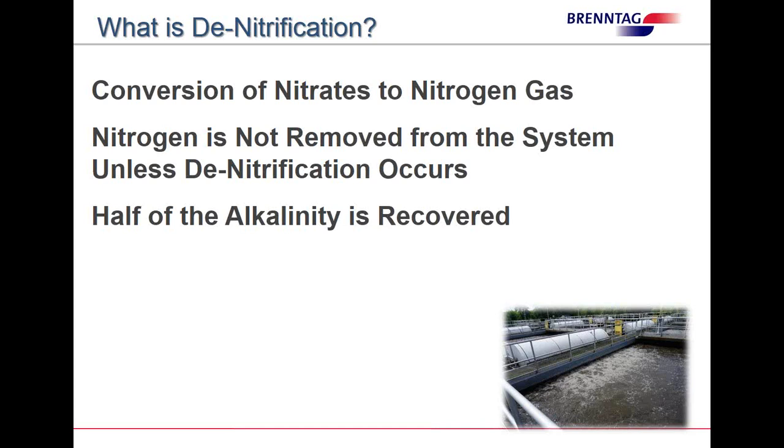Now, when you denitrify, half the alkalinity is recovered. Now, nitrates act exactly like oxygen acts to bugs. Oxygen is the energy that makes them go.